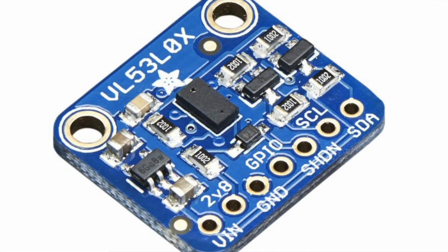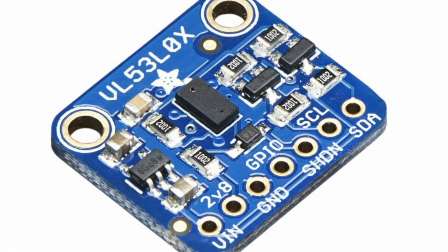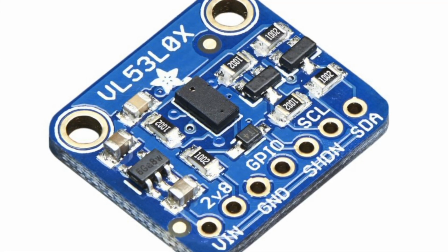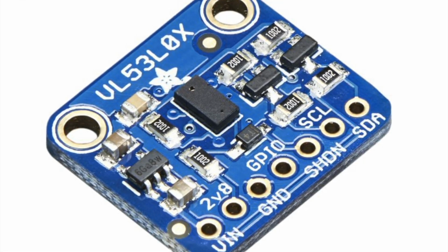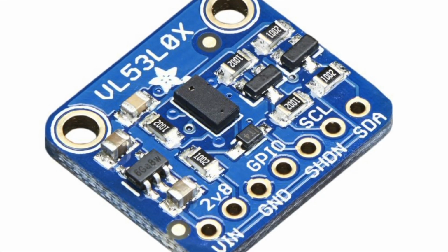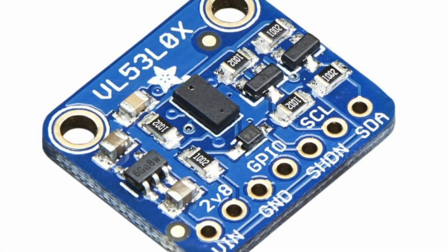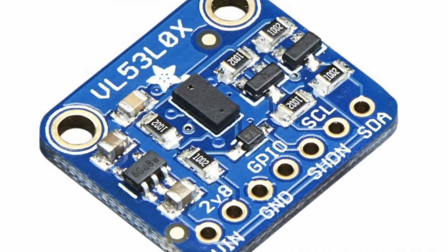One of my favorite I2C devices is the VL53L0X time of flight distance sensor. This sensor measures distances between the sensor and any object or person within 30 millimeters and 1,000 millimeters, or about 3 feet. It's perfect for person detection directly in front of an object, like, for instance, triggering a video or interactivity when someone approaches your artwork.